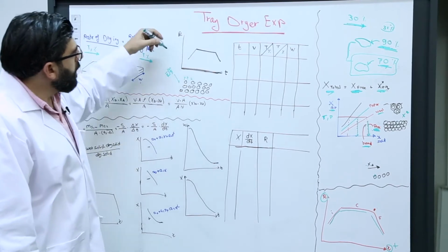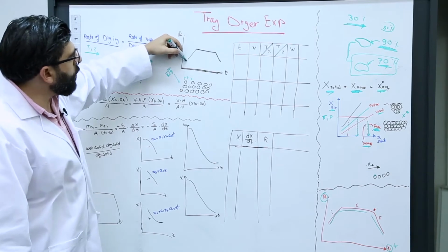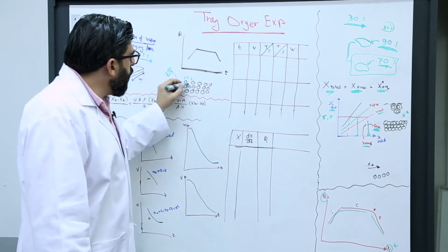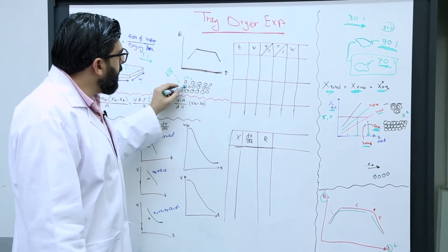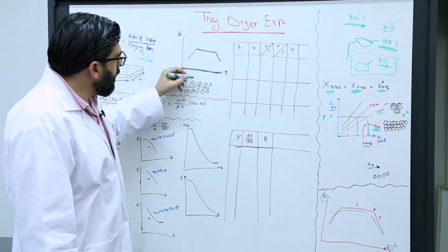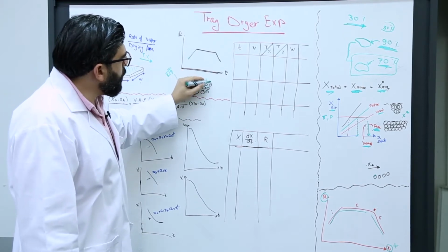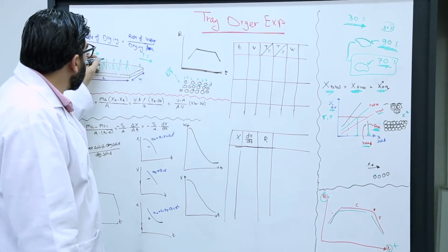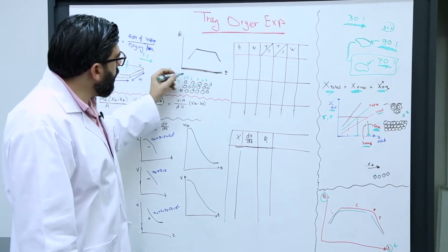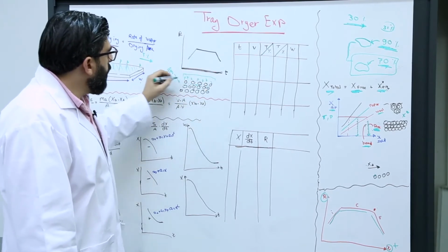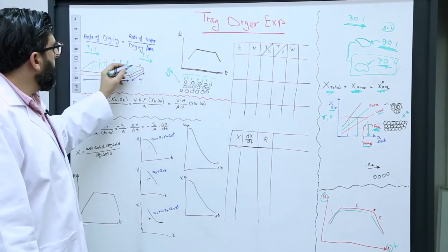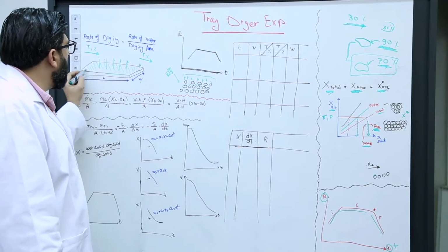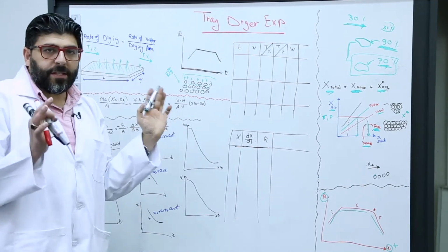So now you will see that the rate of evaporation starts increasing until all the water content in the solid, through the surface area, will be vaporized. So the rate will be constant. Why constant? Because the vapor will cover all the surface. So my limitation is the surface.